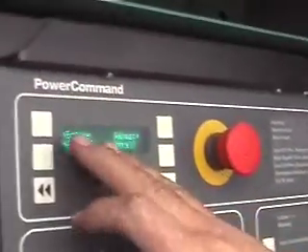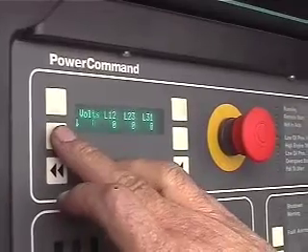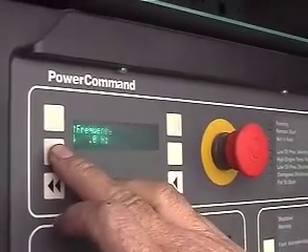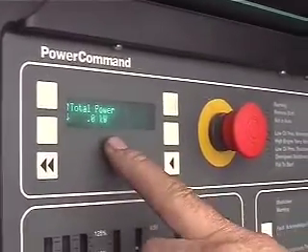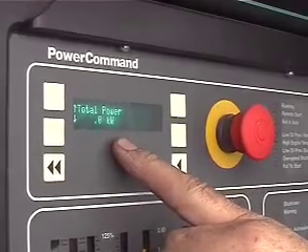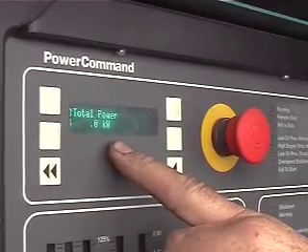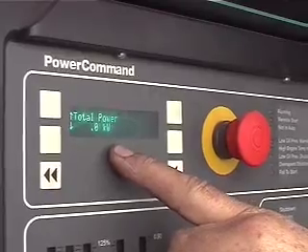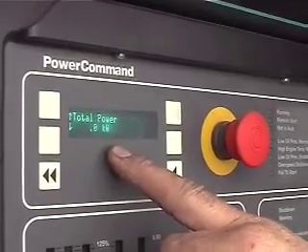When you're on load, you can actually go into the alternator section of this. Then you can scroll down through this. So when you're on the building load, you can come out here and punch this up on your kW, see how many kW you're actually pulling on your building. You want to do that in an audit sometime, just as a curiosity thing, to know what it is we're pulling. By gauging that, you can gauge how much fuel you're going to burn.